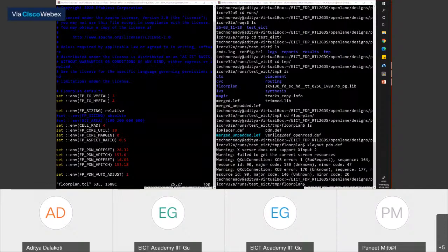The other 80% is not for macros, because macros should be accounted for in your die area already. Some of it is for the clock tree cells, which are not in your design yet. Some of it is because the routers in open source are not very fancy, so they're not able to achieve good routing and placement if your utilization is not low.